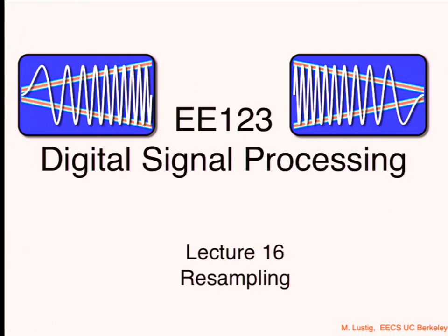If you have some clock skew between two different machines, you record something on one machine, but it's not exactly the same on another machine. It's very, very common, especially if you buy one of these cheap audio devices. And so you have to do some conversion in order to correct for these clock skews. So you have to resample your signal. The other reason that you should be paying attention here, apart from it really being useful, is that this is a source of an infinite number of questions that you can ask on exams. They're so cute and weird and tricky. So, yeah, pay attention.